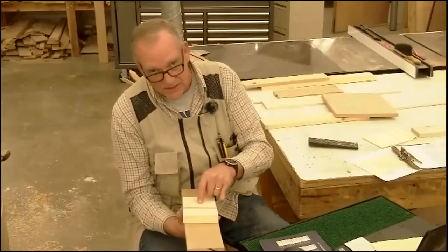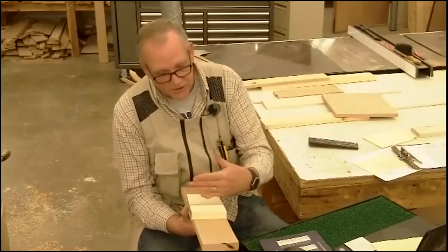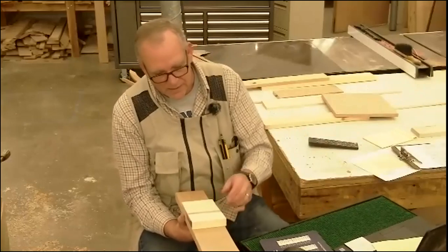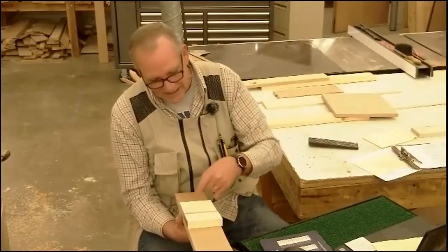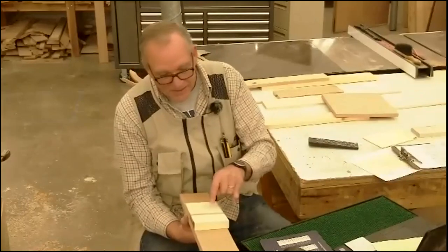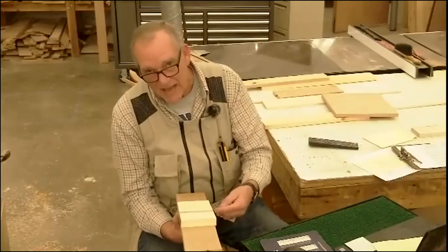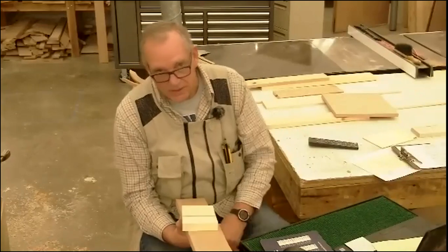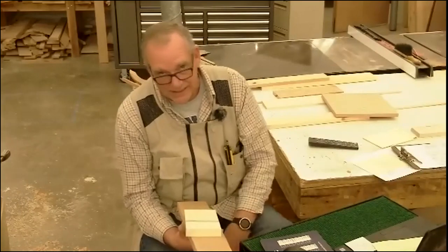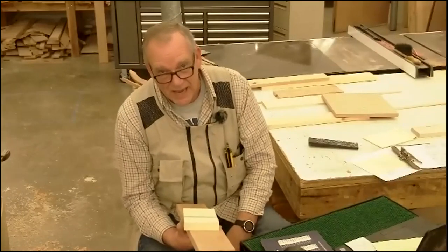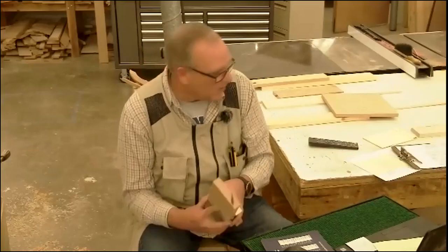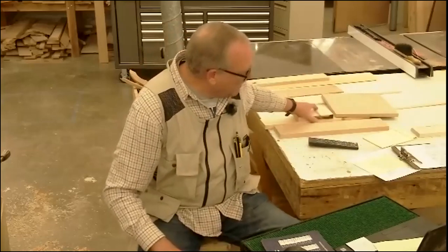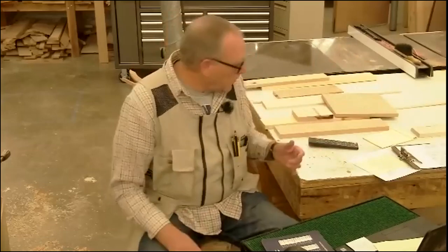But on this piece, the grain's going this direction. So that's a face, that's another face underneath, that's an end, that's an end, that's an edge, that's an edge. But this is face grain, this happens to be end grain, okay? And this happens to be edge grain. This may be called an end, but it's exposing edge grain, okay? We do not joint end grain, and there's a couple basic reasons why we don't, okay?